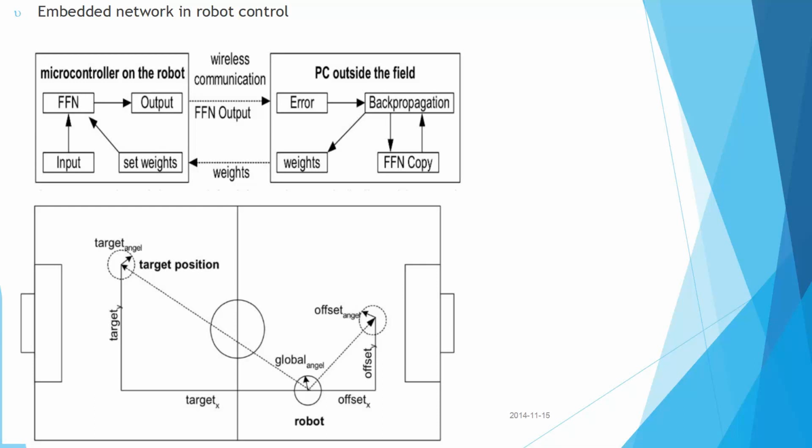This configuration considers 3 robot positions labeled global, offset, and target. The first robot corresponds to the position as provided by the image processing system. It's the global. The second position, called offset, corresponds to the robot's true position, and hence includes the travel distance during the time delay.